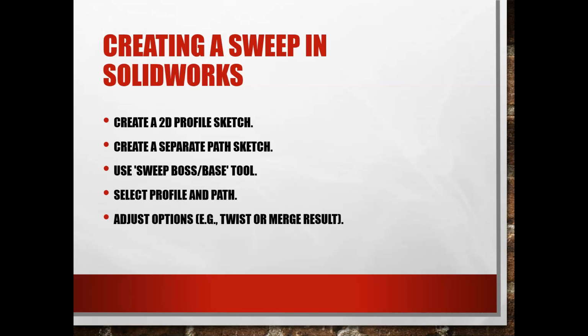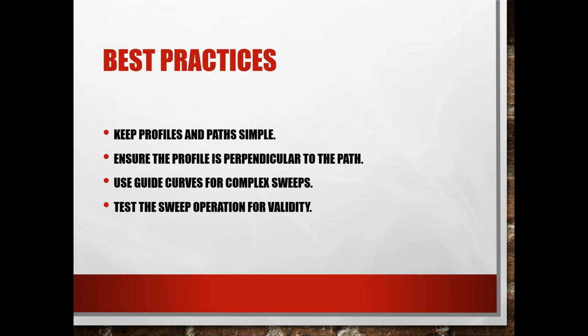In AutoCAD, you're going to have to use the Boolean operation to join them together. And if you're talking Inventor, you're going to have to use the join button when you're actually in the extrude or the sweep or whichever command you're going to be creating.